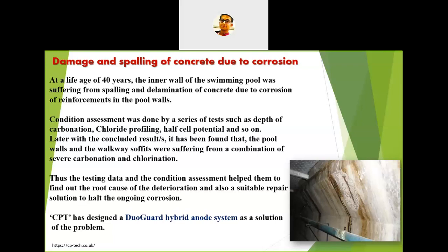The most prominently adopted technology is the anodic system. What happens in the concrete corrosion cell, we have seen, is that the anodic part of the reinforcing steel is getting corroded, or deteriorated. So they introduce some artificial anode, which will corrode instead of the steel bar.